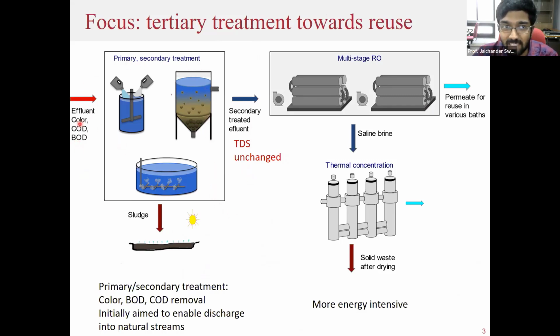The way I think about it is that in the water that comes out after the secondary treatment, the dissolved impurities are more or less going to remain unchanged. So that's why I'm highlighting here that the total dissolved solids remains unchanged. And that is where the desalination technologies come in as a tertiary treatment technology to enable recovery of not just pure water for recycling, but also potentially other resources for recycling in the industry.